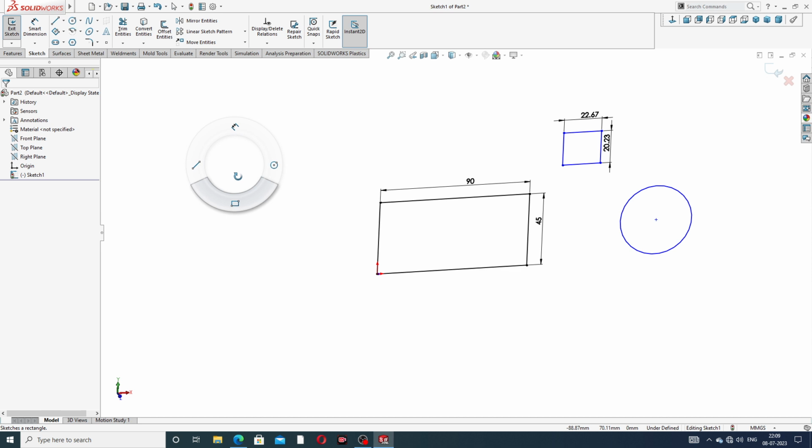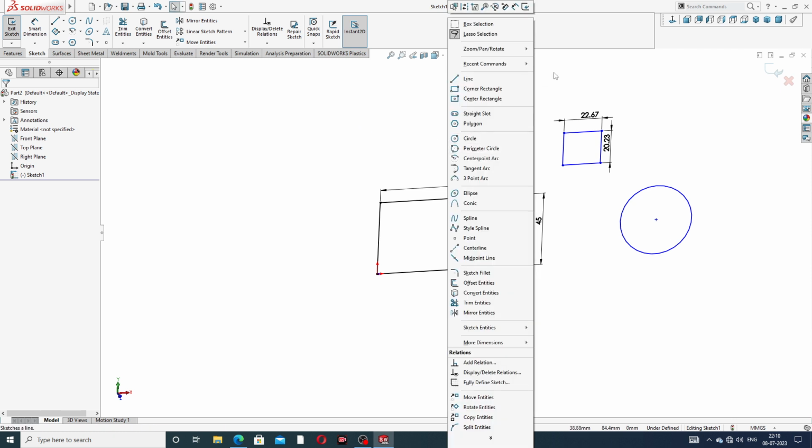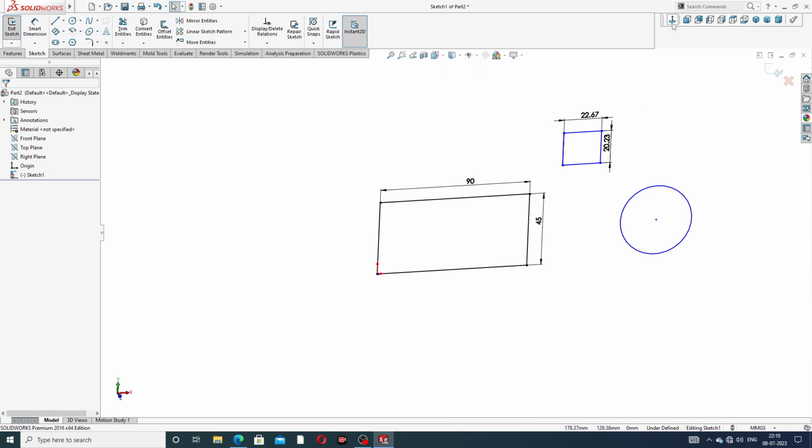This is a circle, okay, draw any circle here. And again select, press the middle mouse button and right click and drag here, and use a line and circle, a line and dimension one by one, all is perfect. Okay, and next is delete here.